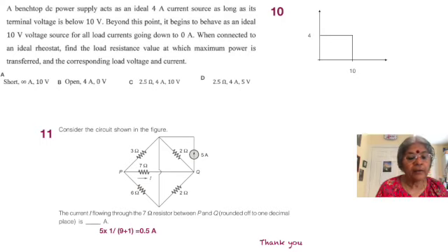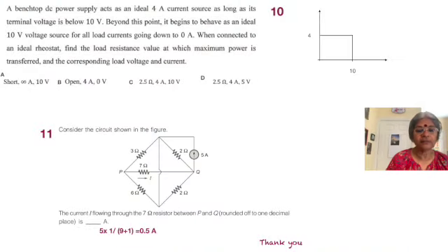What is the other? We have 3 and 6 in parallel. So 3 times 6 over 9, that is 2 ohms, and then 2 ohms and 7 ohms in series, so 9. So 5 into 1 divided by 9 plus 1, or in other words 0.5 amps. As simple as that. So we have used mostly the tricks of the trade to fit together data and arrive at solutions. I hope the different ways in which we fit together are clear to you.